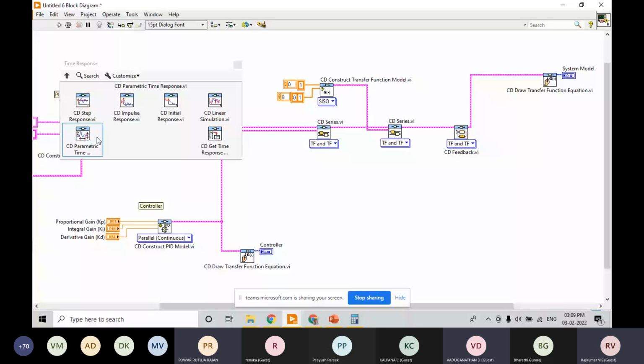Okay, apart from getting the waveform, we need to check how it works in terms of measurements, like what is the rise time, and what is the percentage of peak overshoot, how much peak overshoot we achieved. All those values as numeric values, if we get them, it's going to be very helpful, right? So, step response. If you want to get a step response of the closed loop system, we can perhaps try going for this function.